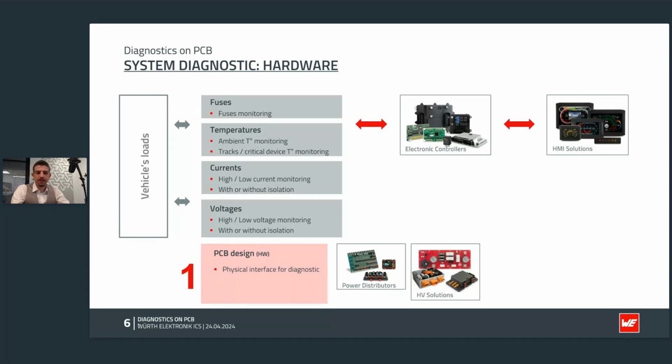The temperature is a limiting factor for many components, starting with the relays. They look very powerful, but let them exceed the room temperature and the performance declines quite rapidly. And for us, especially, the PCB design with its track width, thus temperature elevation generated by current flow, is quite critical too. A surveillance in some critical cases can widely help to prevent things that no one will see too